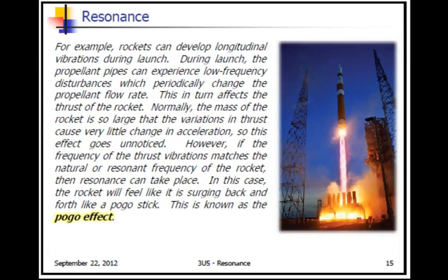We could also see resonance with things that are moving vertically upward. Rockets can have longitudinal vibrations during launch. And during launch, the propellant pipes can experience a low-frequency disturbance, which periodically changes the propellant flow rate. What we end up seeing is what's called the Pogo Effect.